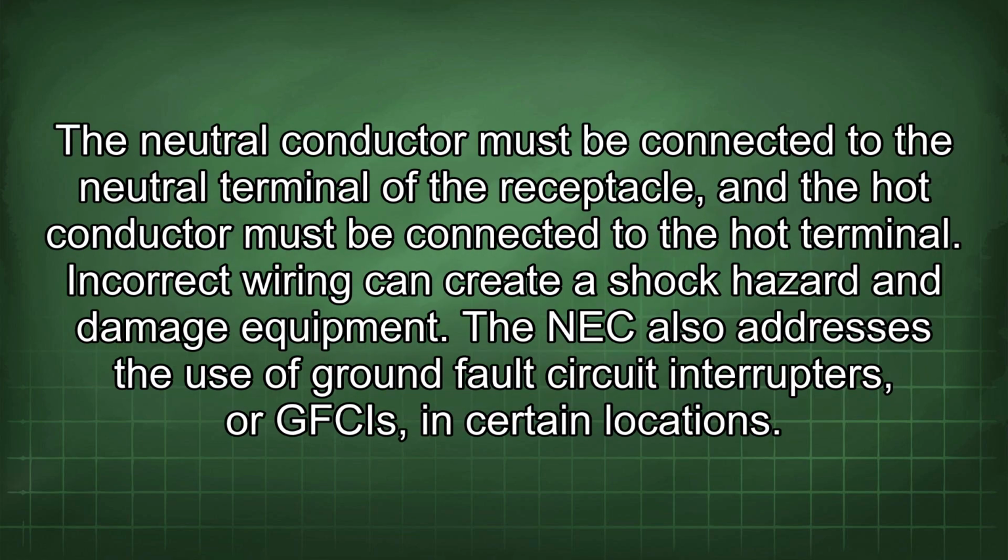The neutral conductor must be connected to the neutral terminal of the receptacle, and the hot conductor must be connected to the hot terminal. Incorrect wiring can create a shock hazard and damage equipment. The NEC also addresses the use of ground fault circuit interrupters, or GFCIs, in certain locations.